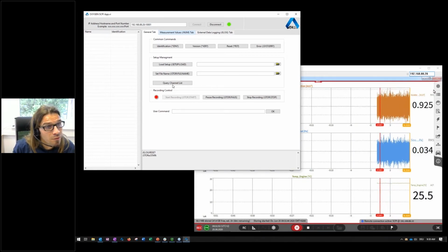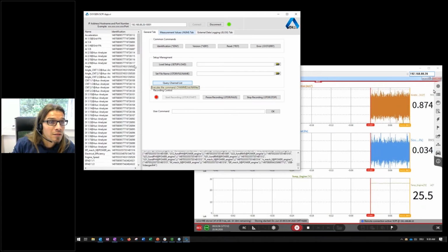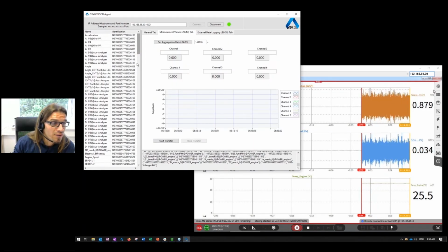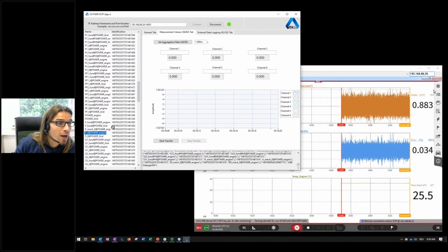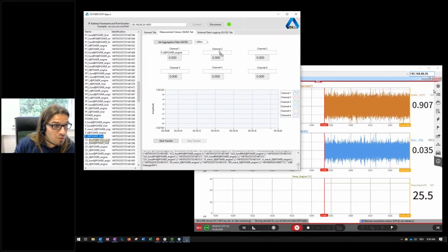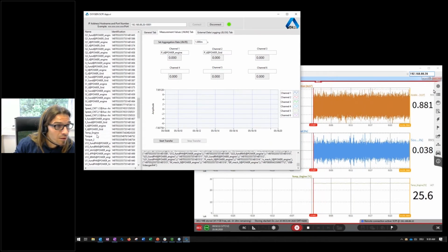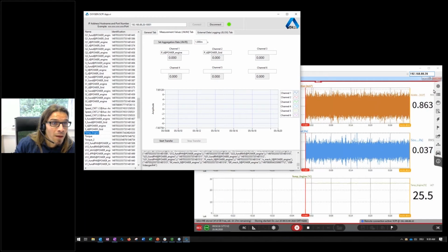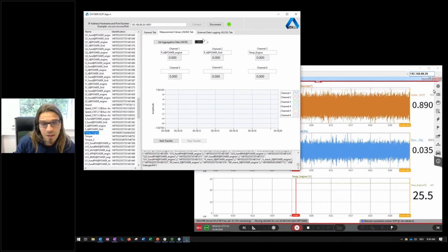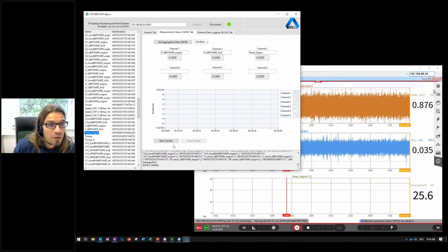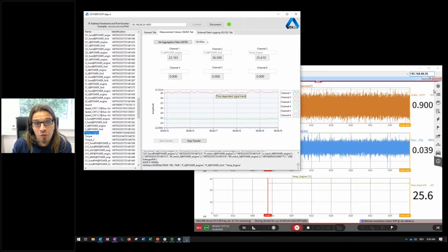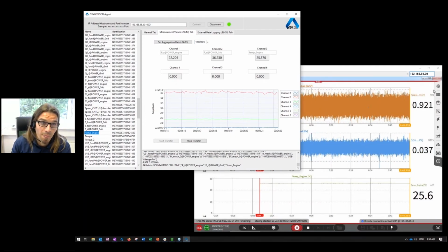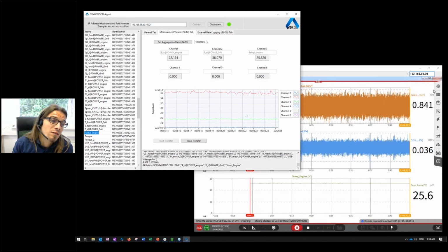I can, for example, also query the channel list, and to show you how the data transfer is working with SCPI, I will quickly drag and drop the active power of the engine and the active power of the grid here to start the data transfer, and also the raw data of the temperature engine. I will transfer the data with 100 milliseconds, and then I just press the start button, and you see here how quickly and how easily you can transfer your measurement data from your measurement device to your test bed, and how easy that can be set up with SCPI commands.